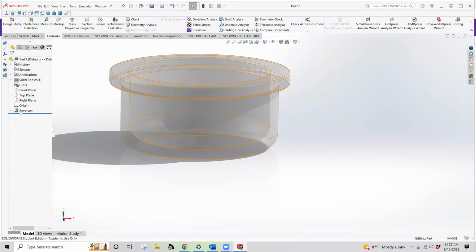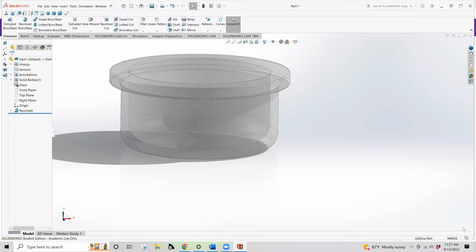It'll also show you information about center of mass and some other things. So this is one of the other ways that we can check and make sure that our dimensions and the part that we're making actually make some physical sense. Because if that weighed 152 kilograms, probably we forgot to check whether we were in IPS or MMGS or some other system. At that rate, you might have been in MKS or something. So who knows? But you want to pay attention to switching those over each and every time you go to do a new sketch. All right, so there's an example.